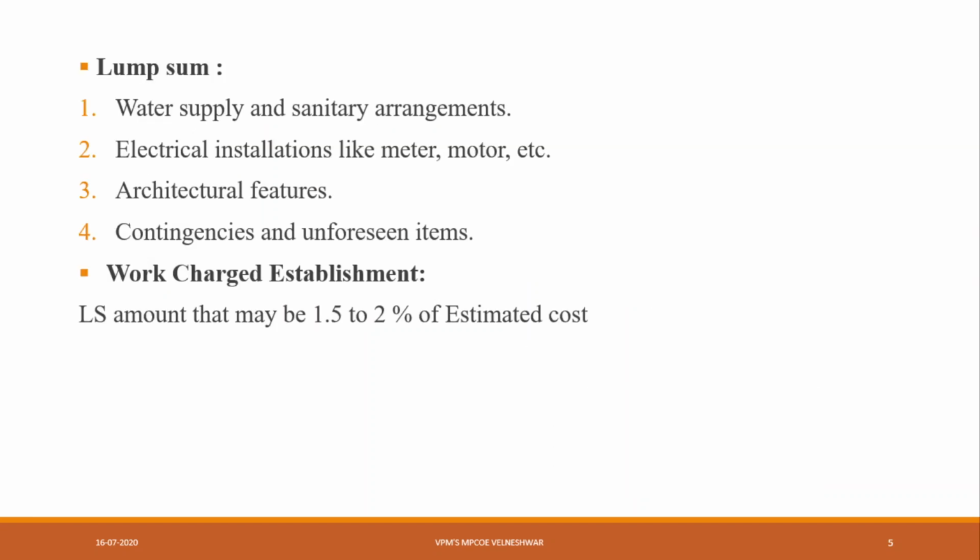Now what is meant by lump sum? We'll see what is meant by lump sum amount. While preparing an estimate, it is not possible to work out in detail in case of petty items. Means there are some items that cannot be counted in your estimates, that happen accidentally in your project. The items other than civil engineering, such items are called lump sum items, and the amount required for those lump sum items is called a lump sum amount, right?